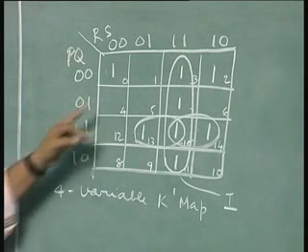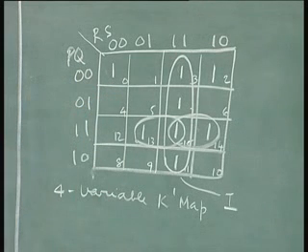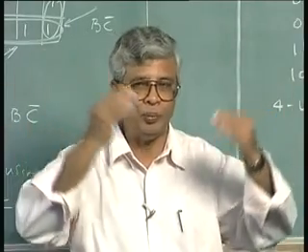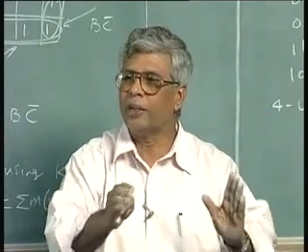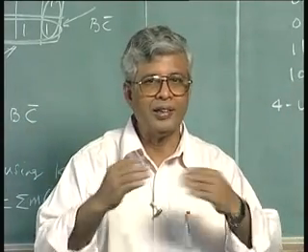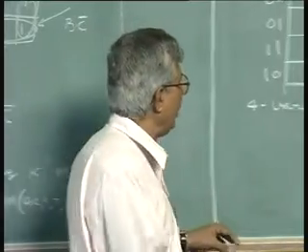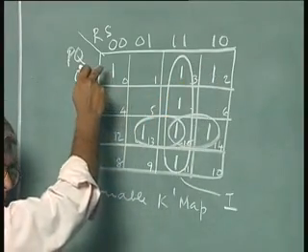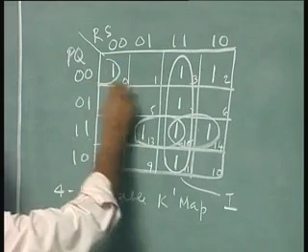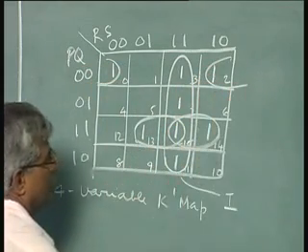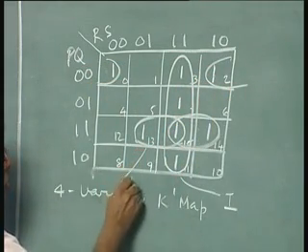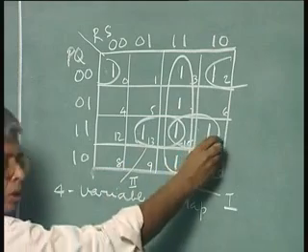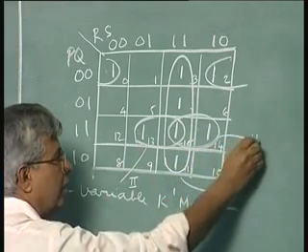So cell number 0 and cell number 2 are adjacent, even though they are physically not adjacent. Physical adjacency is different from logical adjacency, and we are talking about logical adjacency. So I don't have to mix this here, since this is going to be combined anyway. So I will combine these two. I will call this 2, I will call this 3.